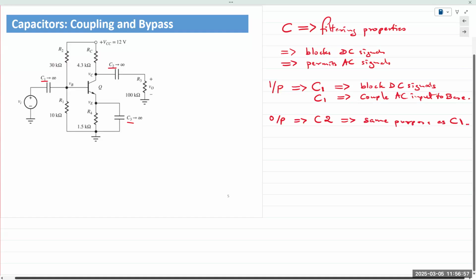Yes. C1 to go to 0. I mean, the reactance, of course, of C1. What do you mean C1? The value for C, like you mean 0 microfarads? Yeah, when you have a low frequency that's like 0 microfarads. No, but with 0 microfarads, you're not connecting anything. Capacitors are very small anyway. The reactance of C1 goes to infinity, or the impedance of C1 goes to infinity, not the value of the capacitor. The reactance and the impedance go to infinity.